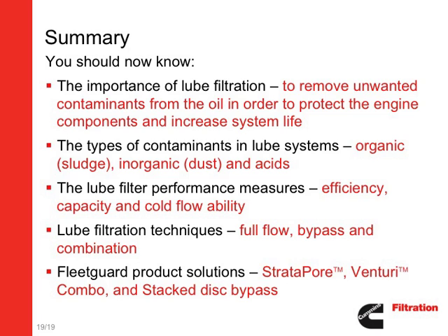You should understand the 3 lube filter performance measures: efficiency, capacity, and cold flow ability. You should have learned about the different lube filtration techniques, including full flow, bypass, and combination filtration. Finally, you should be aware of the Fleetguard line of product solutions for lube filtration, including Stratapore, Venturi Combo, and stacked disc bypass filters.